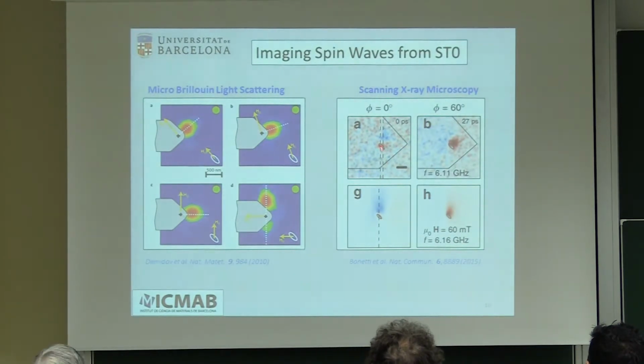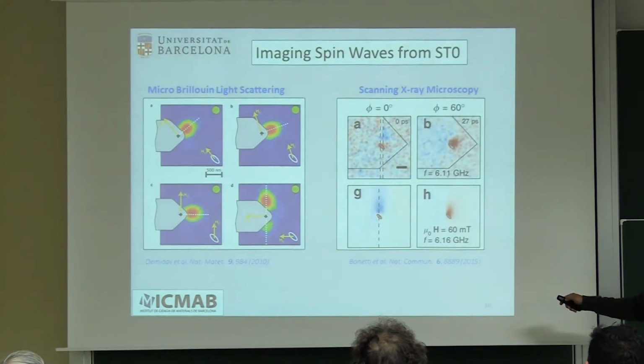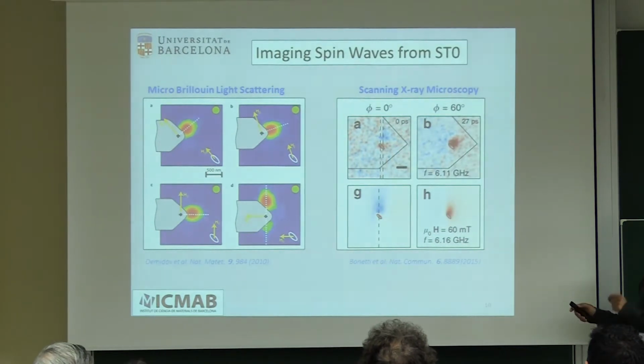So this is the spin-torque oscillator, and instead of having the radiation everywhere, which is probably there at a higher order, all the spin waves are localized in a particular direction. This is because of the effective field, so you have a landscape of effective field, and that focused on a particular direction. So here we have a combination of Ørsted fields plus the dipolar fields of this guy, because this is a pattern fixed layer.